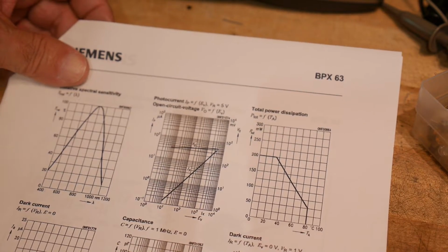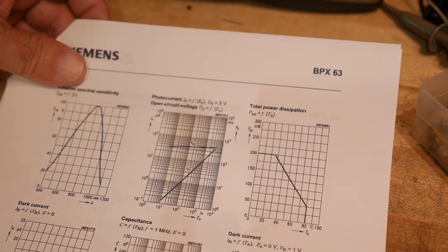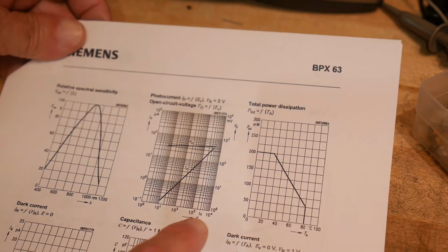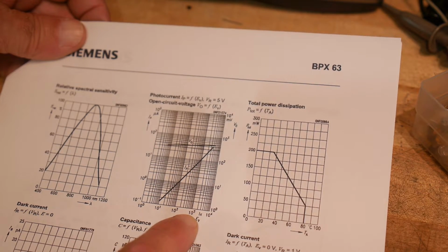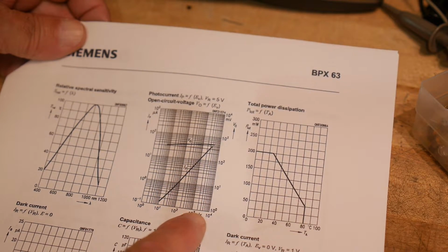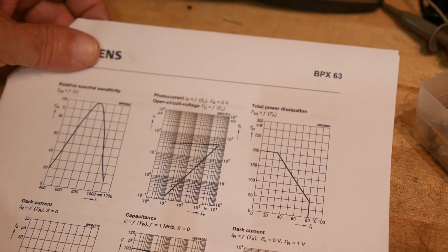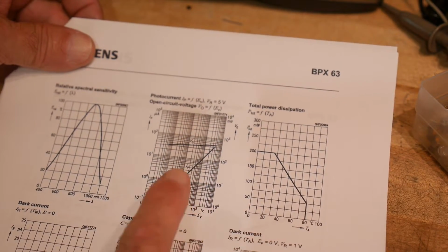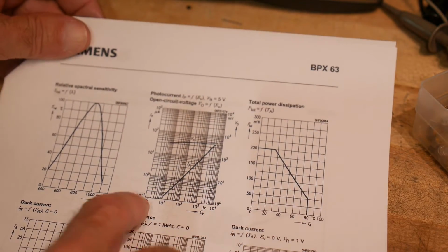Operating rooms actually have a standard. In an operating room, we have to have very, very bright lights, and there's a standard for how many lux of light you have to have. So this goes between 10 lux and 1,000 lux, a couple thousand lux. The sun outdoors is about 100,000 lux. Very, very bright. So the photodiode works nicely here, linear.